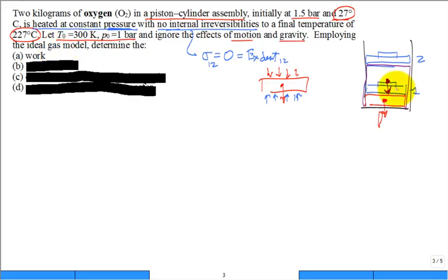So anyway, the focus is on the closed system, which is just the oxygen only. So what is the work that the oxygen does? Does the oxygen do any work during the process? Yeah. What type of work? How do I describe that work? Shaft work? No. What type of work? I'm looking for one word in front of that. Boundary work. What does boundary work mean? It's an expansion work. I'm pushing back the face of the piston. So how do I calculate that work?